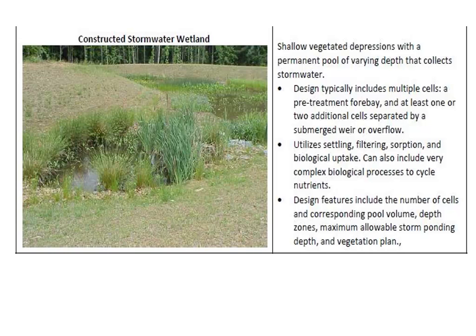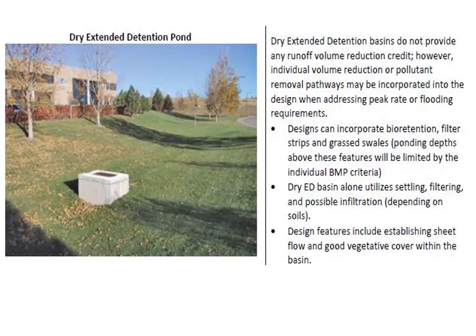All right, a constructed wetland is a way of artificially restoring an area's ability to provide habitat to fish and birds. Migrating birds like ducks and geese really thrive when there are constructed wetlands in an area. But like all the rest of these, the objective is to improve infiltration, to trap water, to slow it down, to give plant contact to the water that's being discharged so that it can take up and deal with the pollutants.